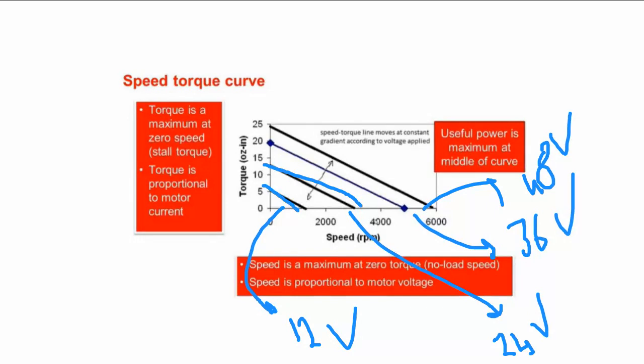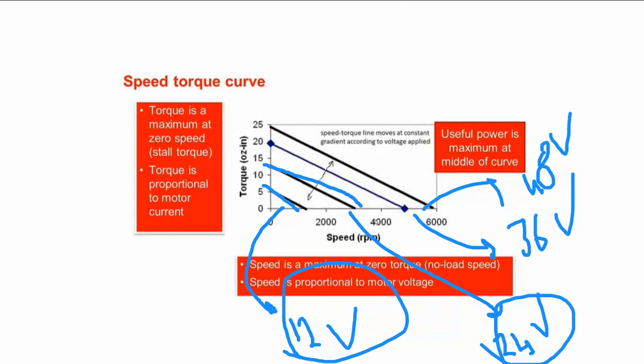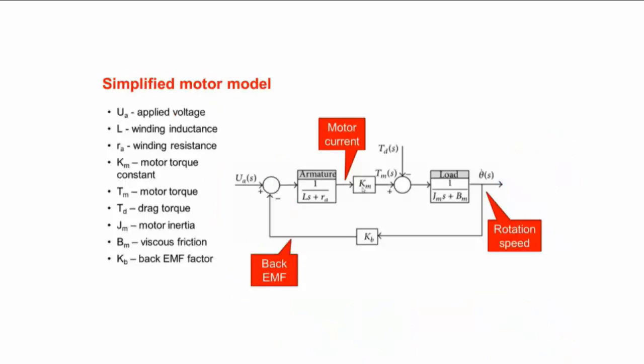Maybe if it was a truck with 24 volt, for example, in a classical traditional vehicle, generally we use 12 volt. In a truck, etc., we use 24 volt. We might have a higher torque and higher speed curve in a truck because our voltage level goes up, and then we can see a high power, high speed curve. And perhaps at a lower voltage, we will have different torque and speed curves.